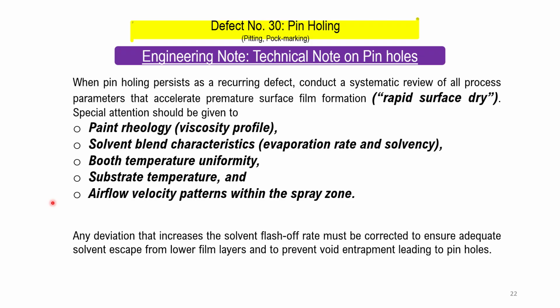Any deviation that increases the solvent flash-off rate must be corrected to ensure adequate solvent escape from lower film layers and to prevent void entrapment leading to pinholes.